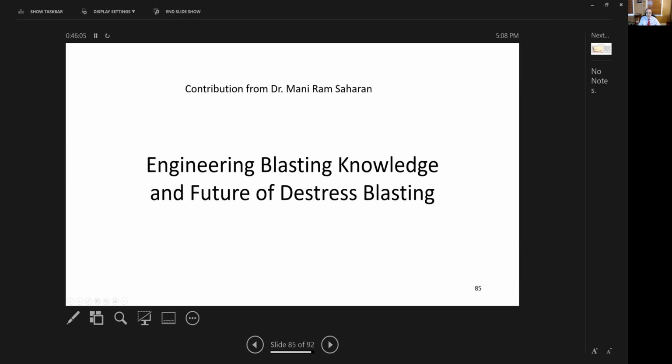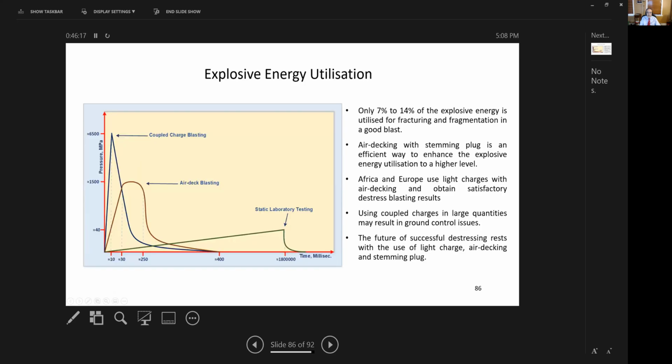I would like now to present two slides on behalf of Dr. Maniram Saharan, on engineering blasting knowledge and the future of distress blasting. So first, only 7 to 14% of the explosive energy is utilized for fracturing and fragmentation in a good blast.